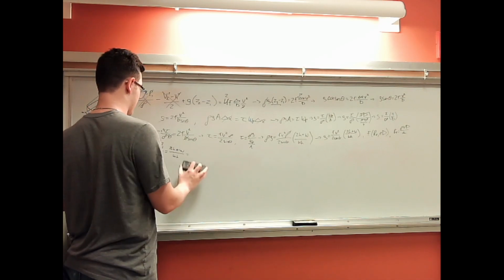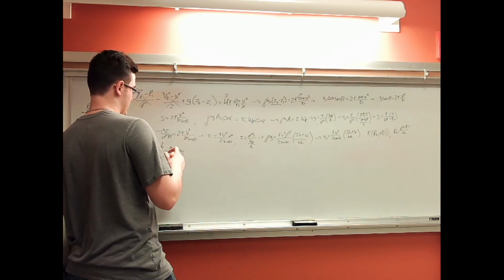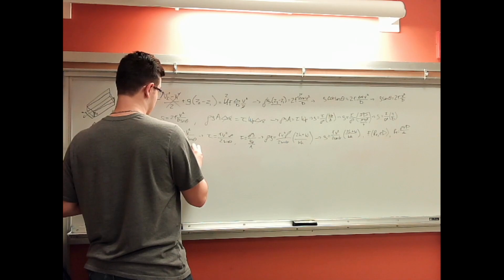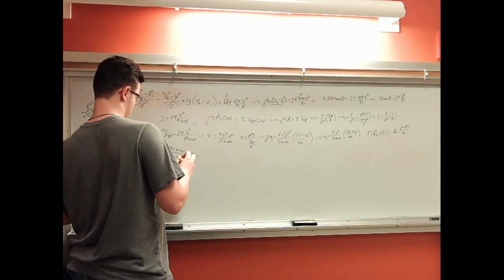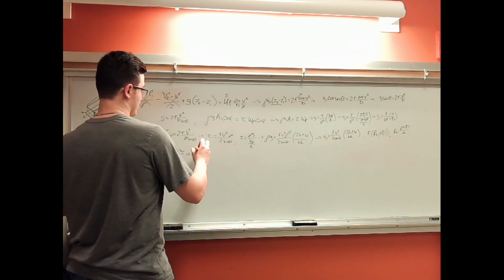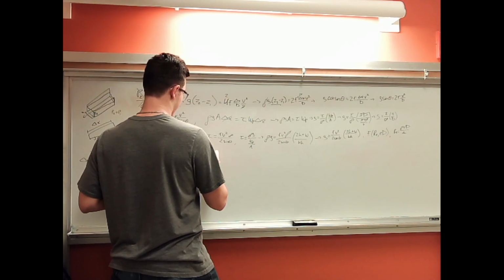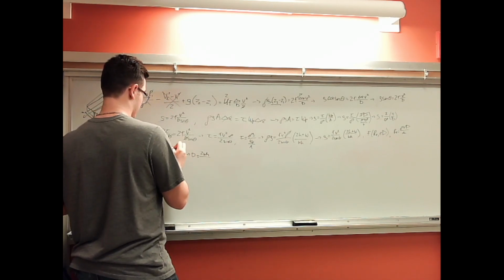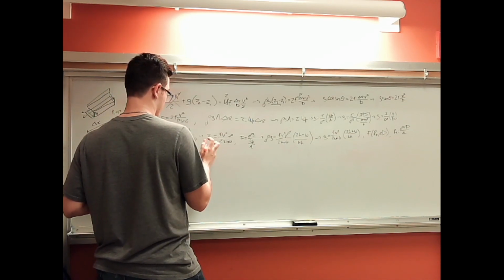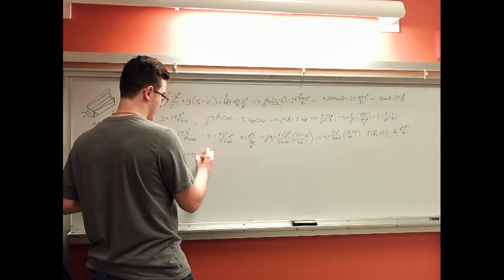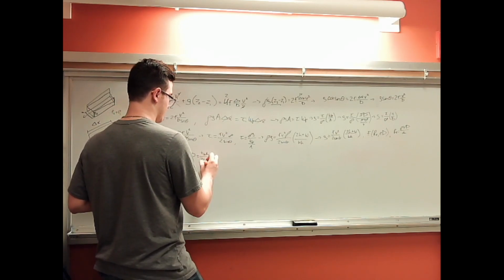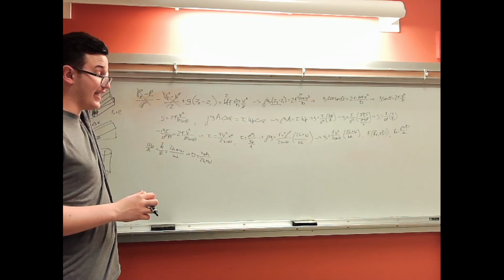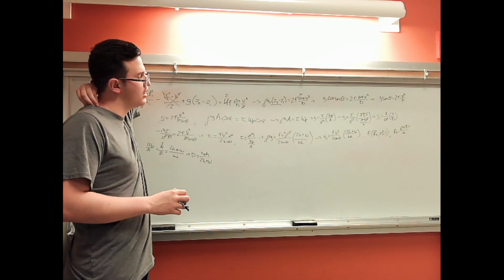That means diameter, if we flip this, that diameter equals 4 times the width times the height, divided by 2 times the height plus the width. So we have this diameter equation here, the diameter of a rectangle, which is kind of weird if you think about it.